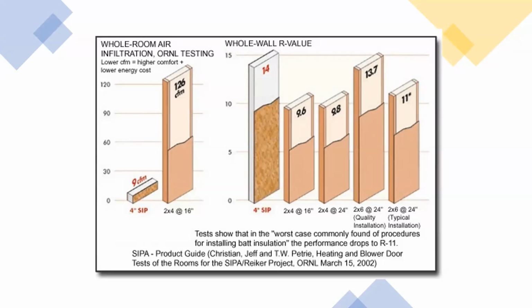So as we see, it lowers the R value the more studs that you have. It's the overall R value in that wall, not each cavity. The models actually take all of this into consideration. They look at the framing, 16-inch on center. They take all this thermal bridging into consideration when it shows the consumption of energy and how to condition the building. It does all this on its own.